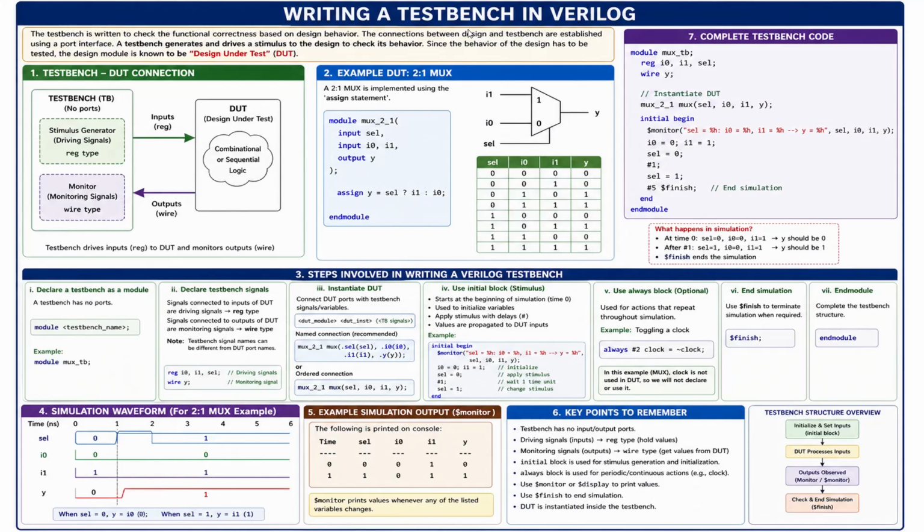So module instantiation should be allowed. That means four modules are there, with different functionalities. I want to represent those functionalities in one area, so I need to integrate all the modules. That is called a hierarchical module. Sometimes we call it a top module, or sometimes a wrapper.